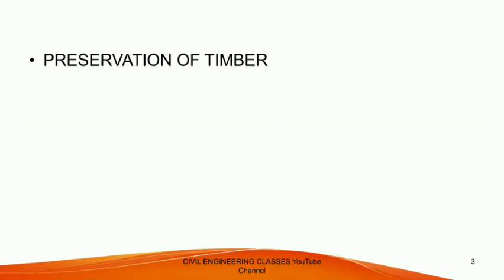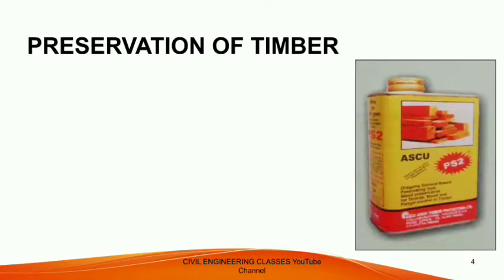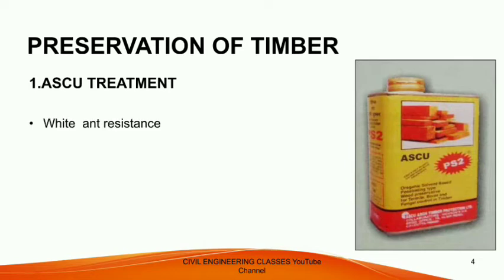Let's see the preservation of timber. In this video, we will also be covering defects in timber. First is preservation of timber. The first method available is ASCU treatment. It is a patented preservative method. It is mainly for white ant resistance.